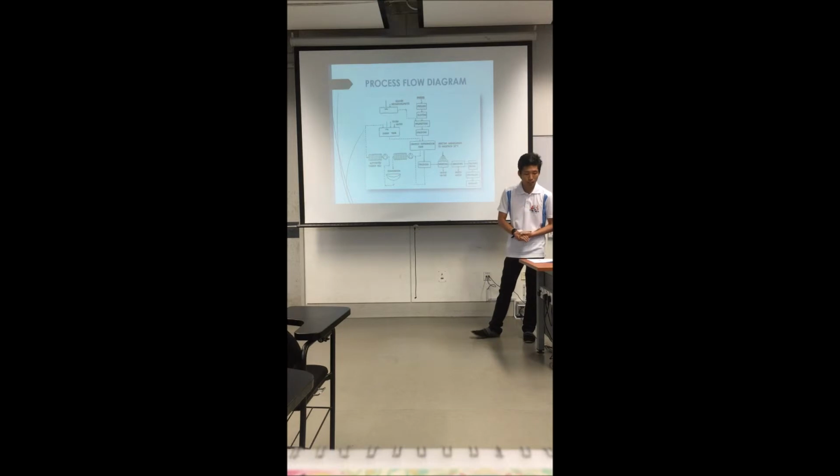Inside the tank, osmotic dehydration takes place, where the water from plant tissue is partially removed by immersion in a hypertonic solution. And the last major unit is of course our vacuum tray dryer, which is used to draw out liquid from the processed raw fruits to inhibit microbial development and quality decay, hence extending the product shelf life.